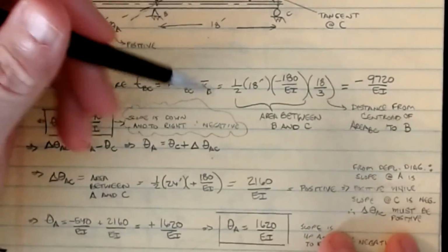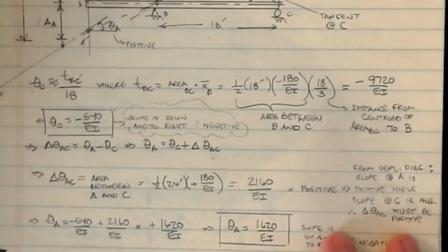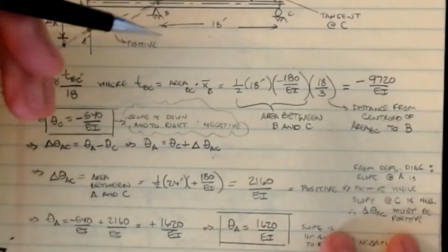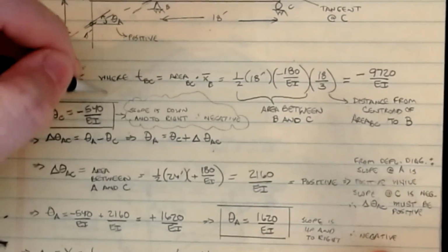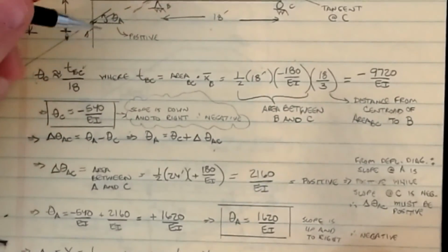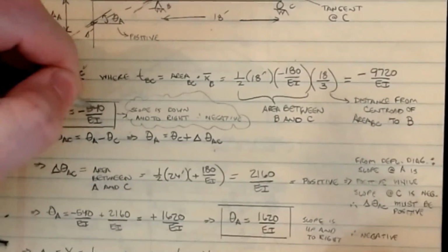Now again, you've got to be careful on the units. There's a foot and a foot in this. So if I want to calculate the actual numerical value, you've got to watch the units. Now we're just doing it symbolically, but you still have to be mindful that there's kip feet squared implied in this top value.